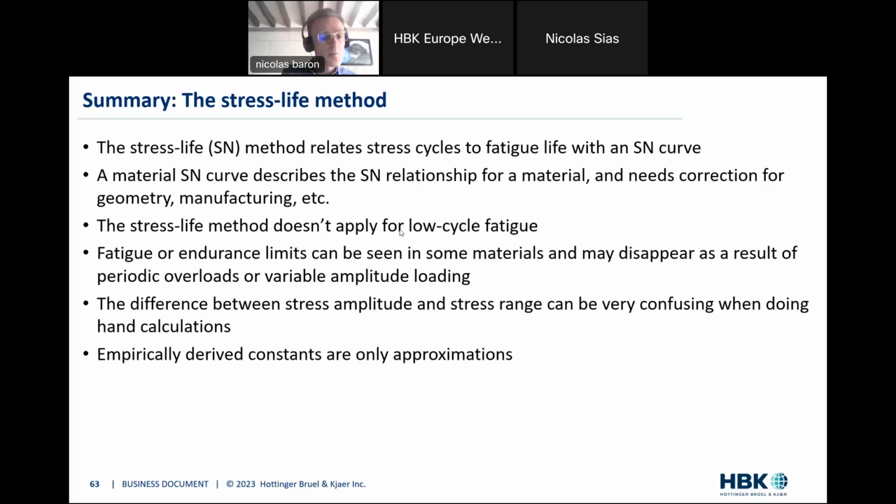And finally, just to reiterate also that fatigue is a statistical phenomenon. We have some probability calculations, probability fits for deriving the curves. So these are constants that we get from experiment, from measurements. So never forget that fatigue is never an absolute value that you give like this. Statistics and probabilities are really baked within your stress result calculations.